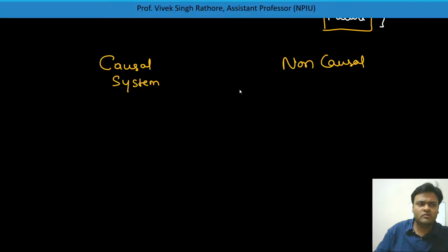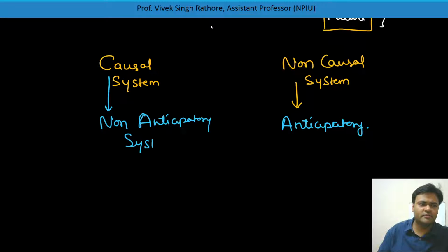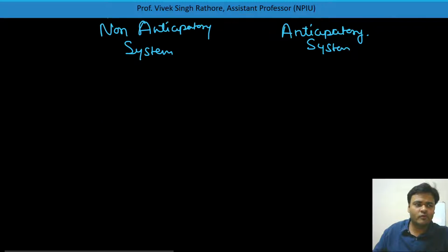Non-causal systems are those systems which depend upon a future value of input also, so they can anticipate the value. So they are called anticipatory systems, and causal systems are called non-anticipatory systems. If you are asked like this, then also you can understand what the questioner wants to ask.